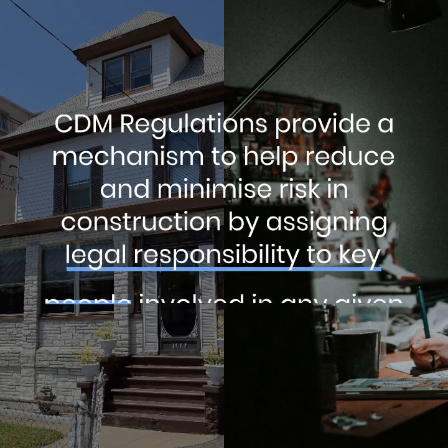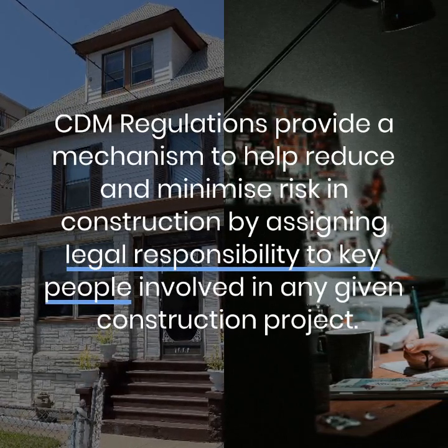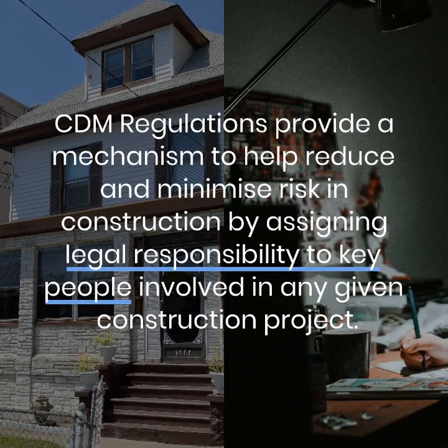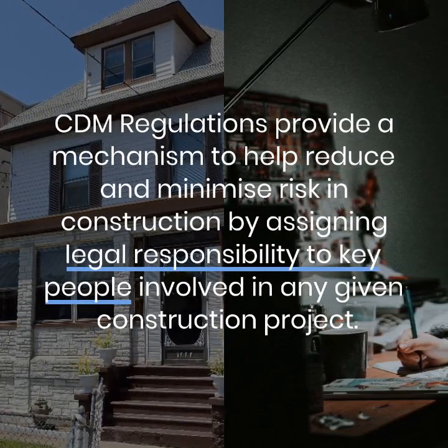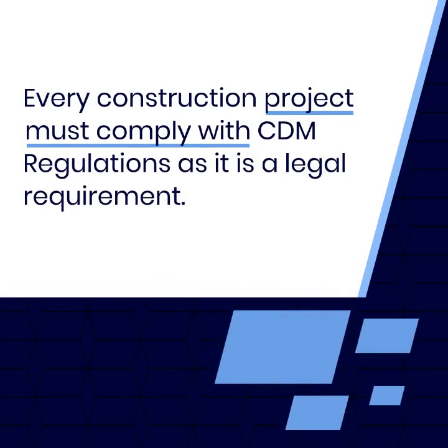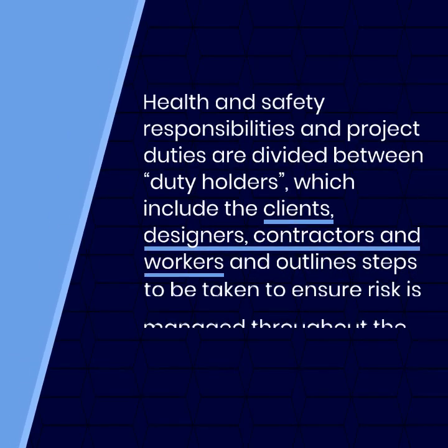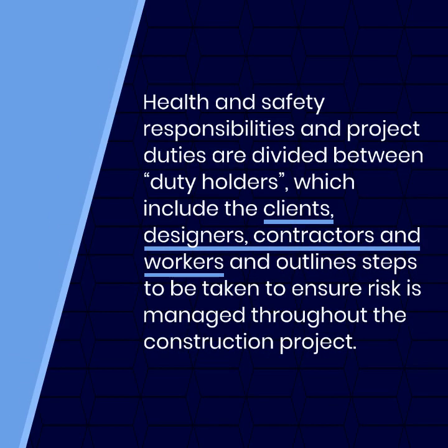CDM regulations provide a mechanism to help reduce and minimize risk in construction by assigning legal responsibility to key people involved in any given construction project. Every construction project must comply with CDM regulations as it is a legal requirement. Health and safety responsibilities and project duties are divided between duty holders, which include the clients, designers, contractors, and workers. It outlines steps to be taken to ensure risk is managed throughout the construction project.